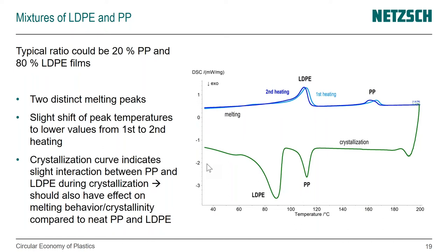If you have really good contact of your sample with the bottom of your crucible, the sample size shouldn't have an effect on your peak shape. If it's packed, and if the heat transfer into the sample is really working as it should, it should look similar. But I'm not quite sure if that captures the effect that you're referring to. So maybe we can connect later.